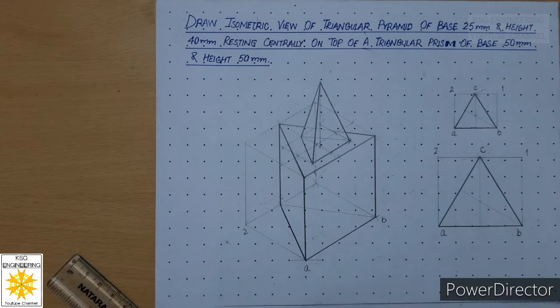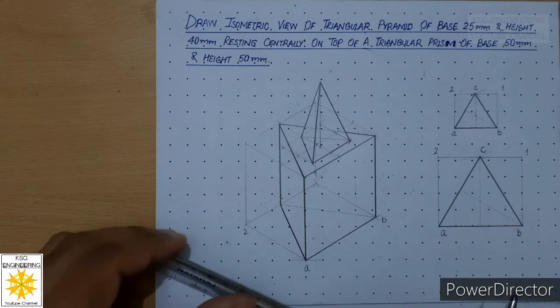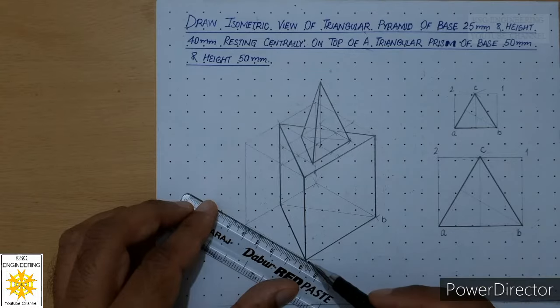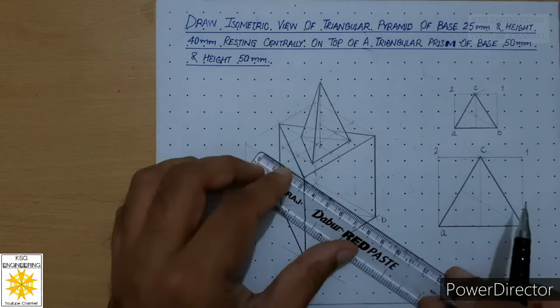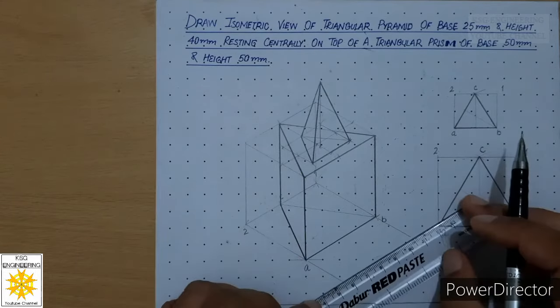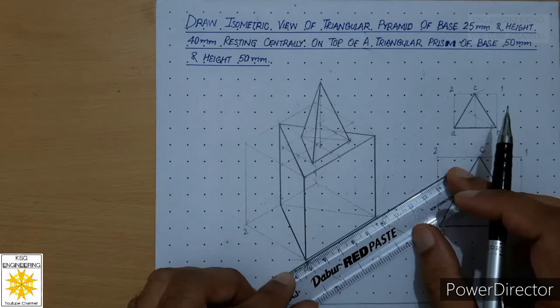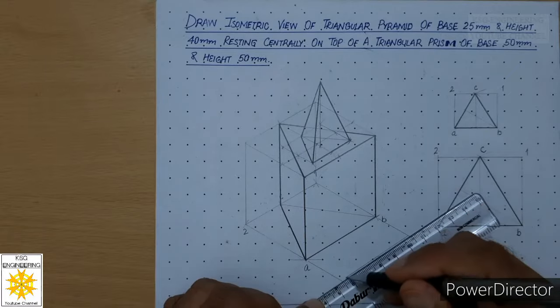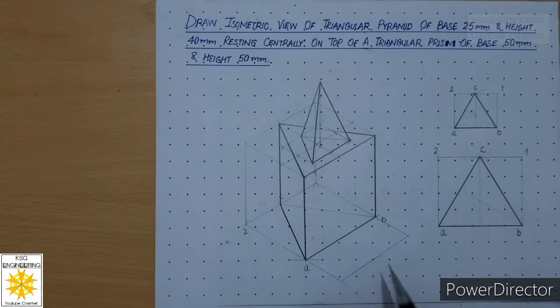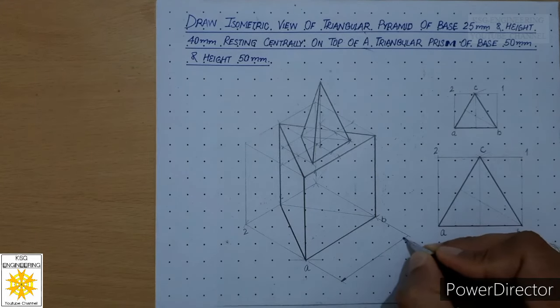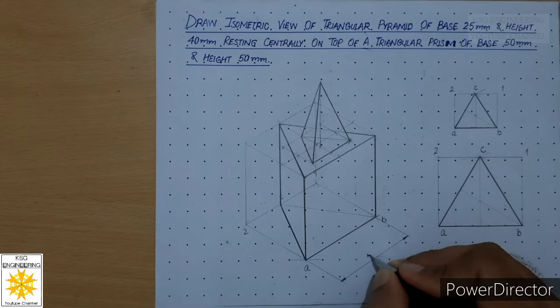Now what we need to do, we need to place dimensions. So let us place dimensions for this prism first. So let us place for its base, which is 50 mm. We will leave a 1 millimeter gap, continuous thin line. Over here also leave a 1 millimeter gap, continuous thin line. We will keep these lines thin. Align your roller scale with this isometric axis, roll back by a few millimeters. Draw the isometric dimension line. So this gap can be 10 or up to 15. Then we will draw closed filled arrowheads on both sides. And we will write 50 in Gothic style.